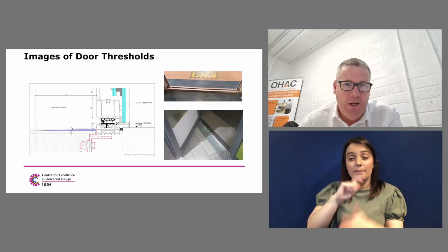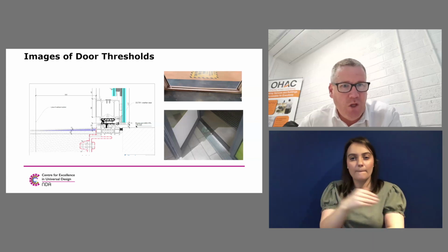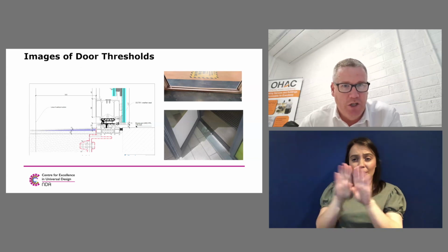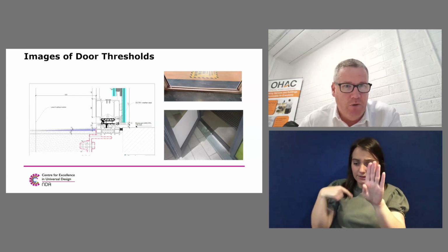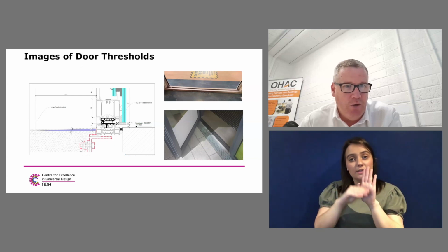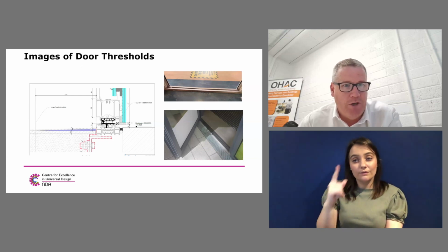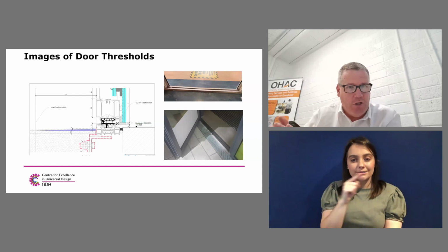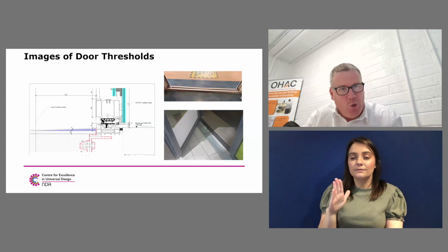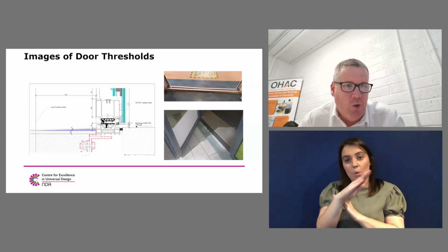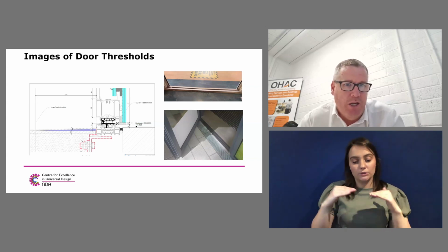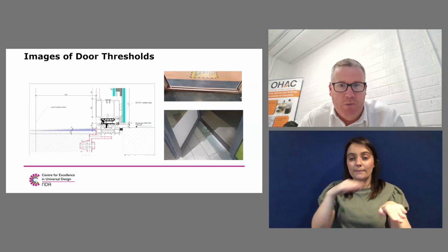And here's an example of a project that we had on site recently. And again, it's quite complex. The door details on the left hand side show you all the requirements and specifications of the door and the thresholds. If you can see the purple part there, where the threshold was above the 15 millimeters, we had to slope gently up into the flooring so that we could maintain a maximum threshold of 15 millimeters.